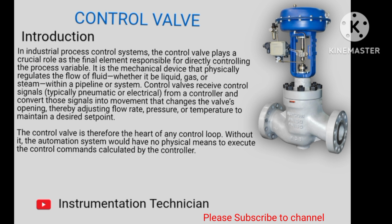Introduction. In industrial process control systems, the control valve plays a crucial role as the final element responsible for directly controlling the process variable. It is the mechanical device that physically regulates the flow of fluid, whether it be liquid, gas, or steam, within a pipeline or system. Control valves receive control signals, typically pneumatic or electrical, from a controller and convert those signals into movement that changes the valve's opening, thereby adjusting flow rate, pressure, or temperature to maintain a desired set point.